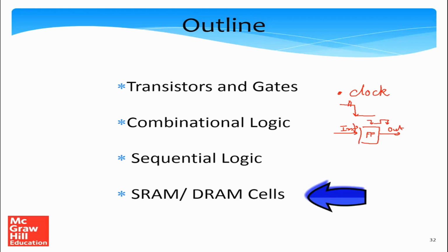The book by Z. Kohavi is one such reference, where we discuss switching theory and a lot of applications of sequential circuits for doing fairly complicated logic. So for example, you want to make a traffic light controller. How would you do it? You'll essentially have a set of flip-flops, and you'll have a clock, and there'll be a set of inputs, and there'll be data moving between the flip-flops, and you can realize complex logic with the help of that. So I'll not discuss this more.